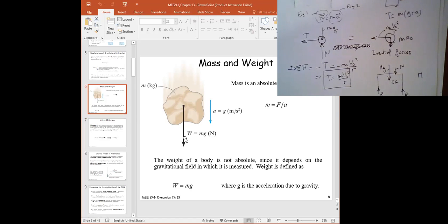You always get the mass by dividing by, let's say, 9.8, but we don't do that in the SI system. In the American system, sometimes the weight is given to you in pounds. So like I said, you divide by 32.2, which is g in feet per second squared, so you can get the mass, because sometimes you want to multiply the mass by V0 squared over R. It's not always g.